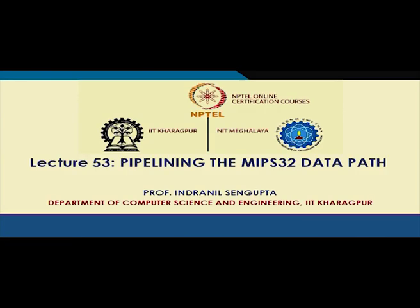So, if you recall, we have seen that there are 5 steps overall to execute an instruction in the MIPS 32: instruction fetch, instruction decode, execute, memory operation and write back. So, we start from there and we just initiate our discussion for this lecture. We shall be exploring the pipelining of the MIPS 32 data path.